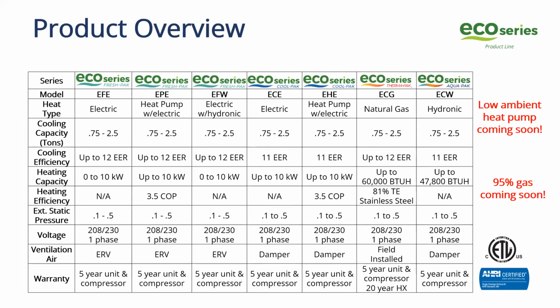But if you wanted consistency across all the apartments, or if it's assisted living or senior housing, you could go with the 9,000 BTU, just put it in the closet and tucked away so that you don't have to deal with the PTAC out in the room, or possibly providing multiple PTACs for one apartment.